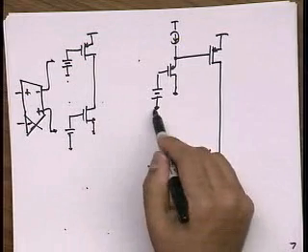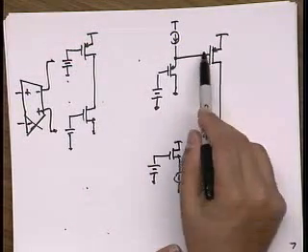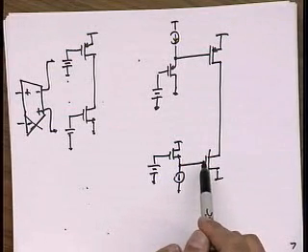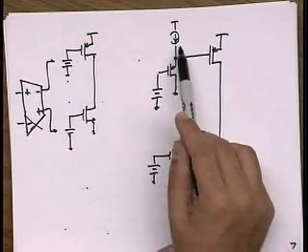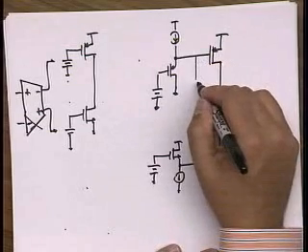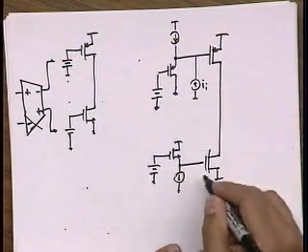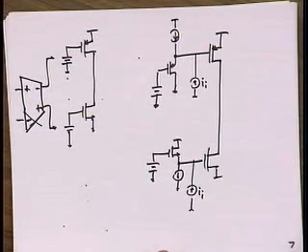So these voltages plus a VGS gives you the right VGS here. This voltage minus a VGS gives you the right voltage here. And now the output impedance, instead of being very low, it's controlled by how much trickle current you put through here. So now I can drive this with my, let's say, input signal.